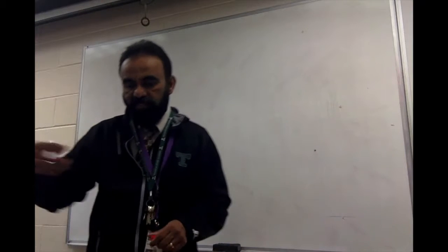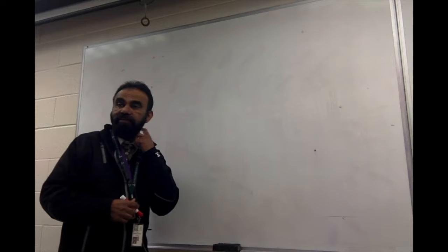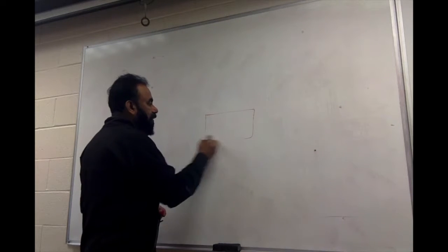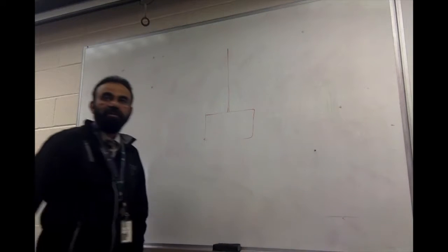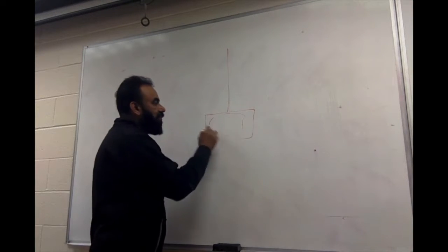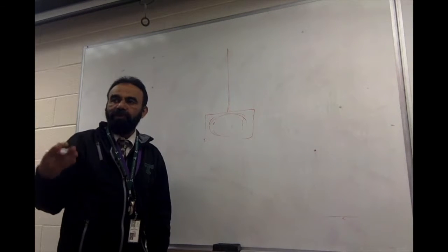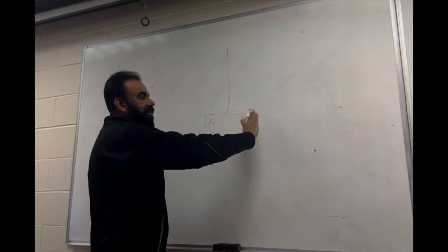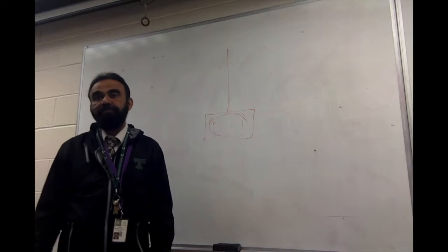So circulatory currents flowing in the material are what cause eddy currents. And how are eddy currents removed? So remember I told you about this pendulum with the sheet metal? If it is basically a solid sheet of metal, you will have circulatory currents going like that all around, and those circulatory currents are going to be flowing in such a direction to oppose the cause. So with this pendulum, the oscillations can be suppressed very quickly.